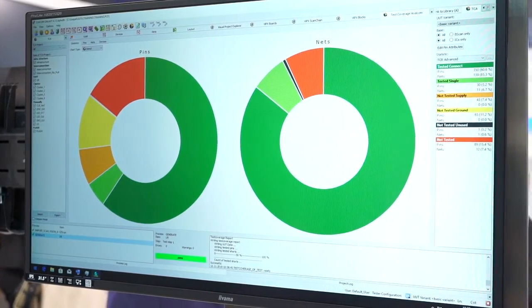We have extended our database, so Goepel doesn't just say it is tested or not tested. We deliver the information on what we have done with all the elements on your board. For example, for pins, which tests give which information and which coverage. The user defines his own test statement, so he has a complete list of definitions for what we call test coverage groups. One group could be, for example, tested, and the application engineer is able to define exactly, with complete Boolean algebra, what tested means for him. That is very important.